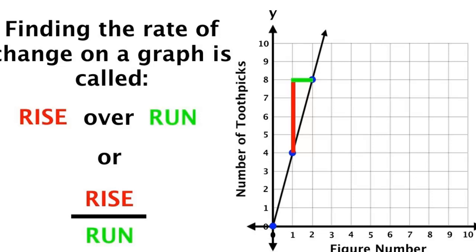Okay, so if we had, say for example, maybe 10 turns on a 1 centimeter diameter core, then the turns here to get maybe 10 volts, you'd need to see something in the order of maybe a 2 megahertz pulse or something like that. So it'd have to be, again, this is from the minimum magnetic field to the maximum magnetic field, and it's all done over time.